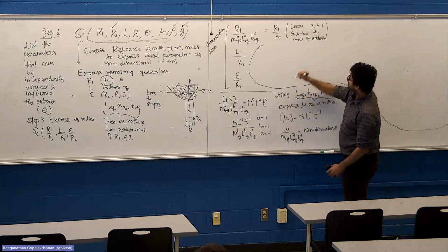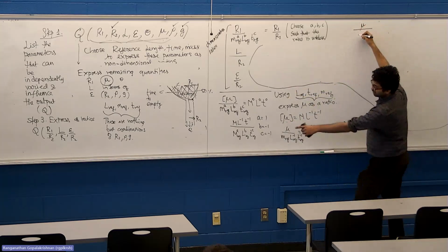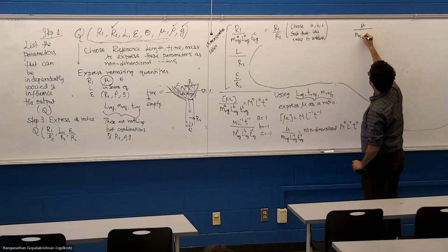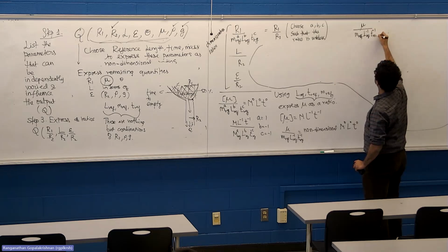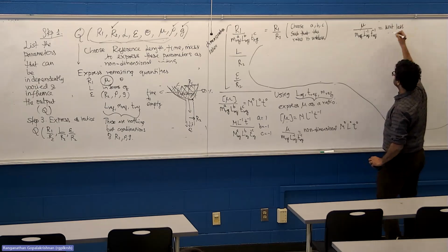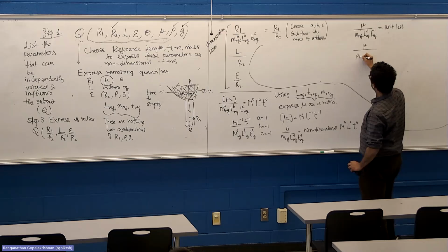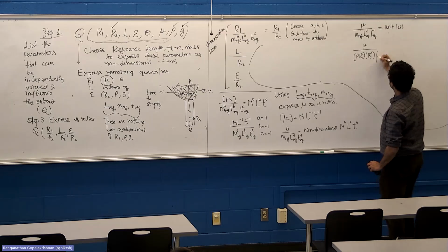So what this means is, if I take viscosity and divide it by m ref to the power 1, and then multiply that with L ref inverse and T ref inverse, this quantity must be unitless. That's what it means, and you can check that. So if we take viscosity, what is m ref? Rho times R2 cube. And what is L ref? R2 to the minus 1. And what is T ref?